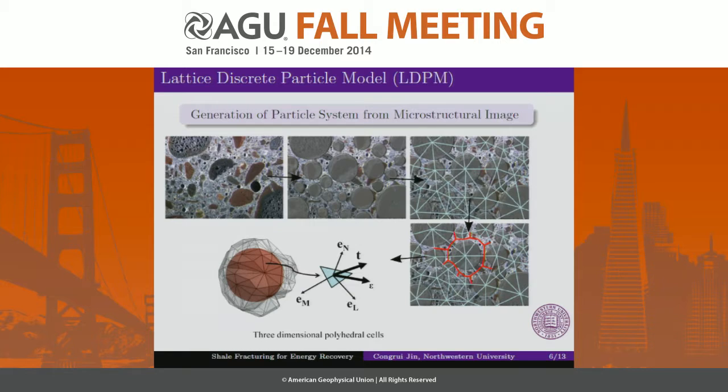We here assume that the fracture initiation and evolution occur in the cement paste between the aggregate pieces, and the aggregates remain mostly undamaged during the loading process. This procedure has proven itself to be very effective in producing particle systems that capture the geometrical features very well, such as grain interlocking. The use of polyhedral particles as opposed to spherical ones in most literature is very important in reproducing the fine geometrical features for cracks, slip planes, and shear bands in quasi-brittle materials.